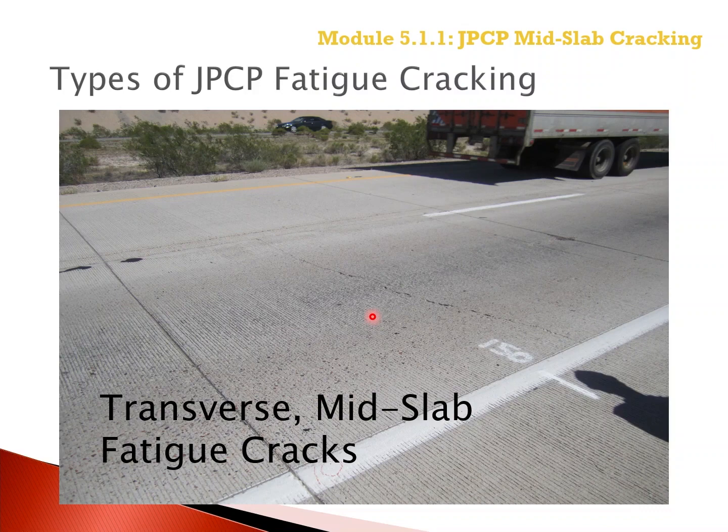The definition of mid-slab fatigue cracks is transverse cracks that extend across the PCC slab. The measurement is simply the number or percentage of slabs with mid-slab cracks as predicted by the Pavement ME design software, and which were used in calibration.